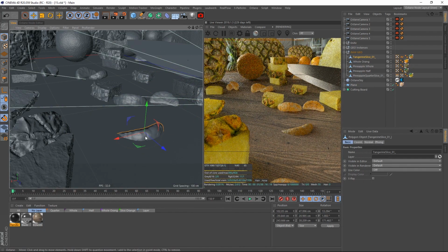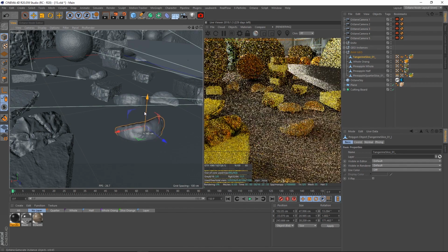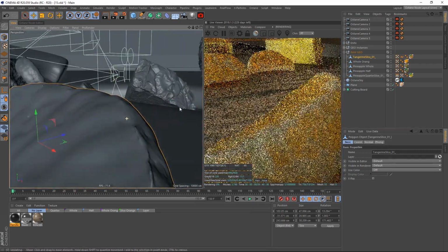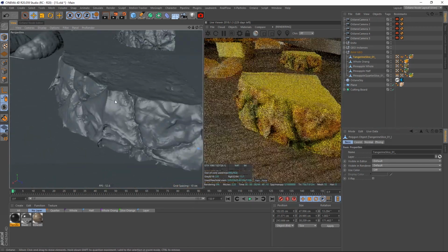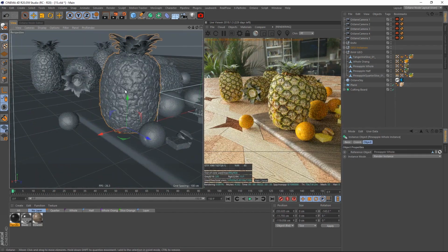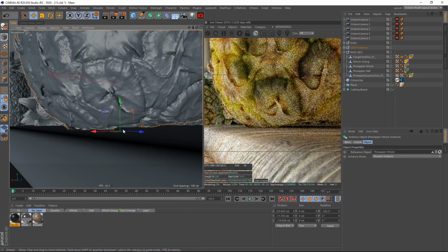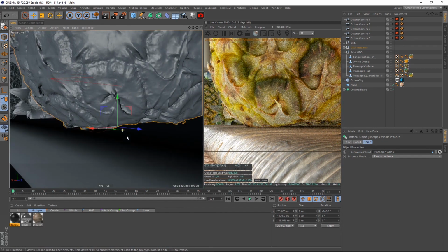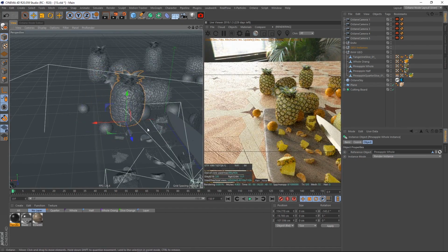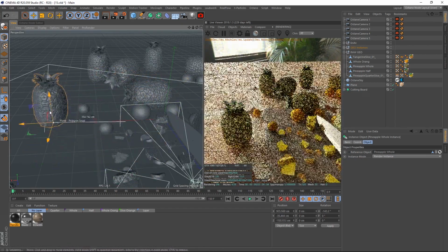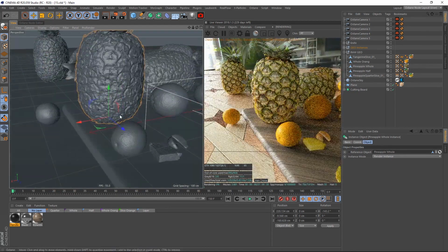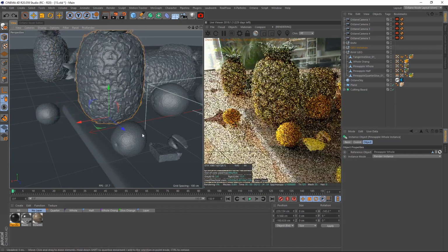Then I'll press Shift plus S to disable the snapping, and lift it up until it's no longer clipping. That said, if the base point of your object is set up correctly, you won't have any clipping at all. For this pineapple slice, for example, I think... no, that's not set up correctly. One of these objects, here we go, this big pineapple chunk, has its object axis set at the base. So this one I can drag around, and if I press Shift plus S, boom, beautiful, perfect snapping on our floor. It rotates around and is very easily placed. So that's a little bonus there. Shift S again disables it, and you can do more free-form movement.